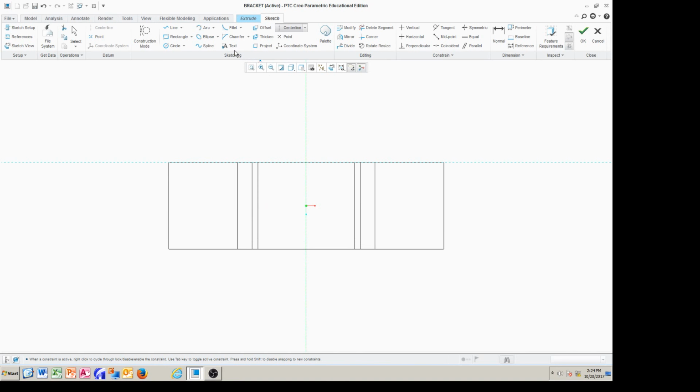So in order to make it snap, I'm going to use the temporary entities. We call it project. I'm going to place it here, and I'm going to use center line, and look at that. Now it's going to snap. Look at it snap. It says midpoint. Yes, we are interested in a midpoint, because that cylinder will be placed at dead center here. So do not forget to delete or trim that temporary line, because it's going to cause all kinds of headaches, because it doesn't let you extrude your feature.